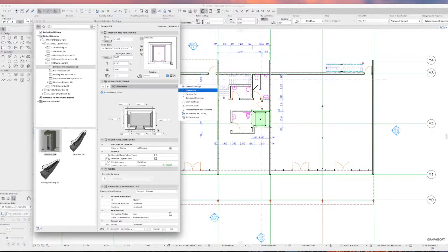So when you've got your dimensions from your elevator supplier, you can then just place these. Now the important thing is you will want to turn on show elevator shaft. Otherwise I think it's just a 2D thing. Well, it does actually put a 3D model of the car in, but you don't get the openings in the core wall unless you turn on the elevator shaft. You don't get the openings in the elevator shaft wall with the call panels and things like that unless you show elevator shaft. So if you show the elevator shaft, then you can fill in all your dimensions from your elevator manufacturer, elevator car information, door styles, whether they're centre opening doors, and some heights, etc.